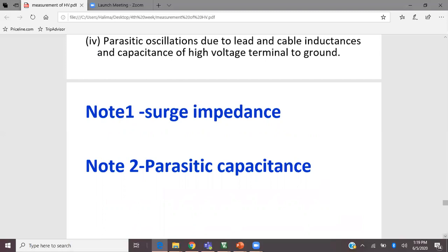The characteristic impedance, surge impedance, can be determined by the geometry and the material of the transmission line. And for a uniform line, it is not dependent on its length, and the SI unit of characteristic impedance is the ohm. I am again repeating, it is the ratio of the amplitude of the voltage and the current of a single wave propagating along the line, traveling in one direction in the absence of reflection in the other direction. It can be determined by the geometry and the material of the transmission line, and for a uniform line, it is not dependent upon the length.